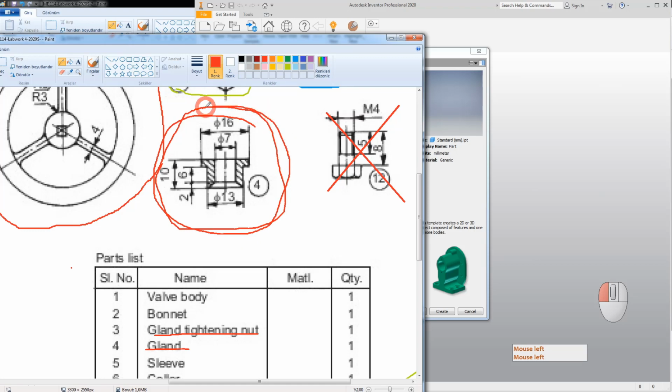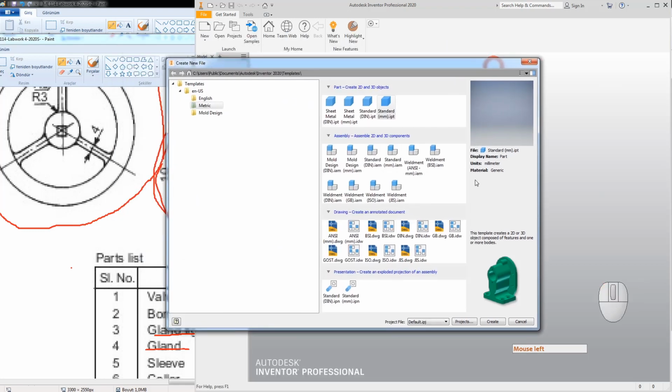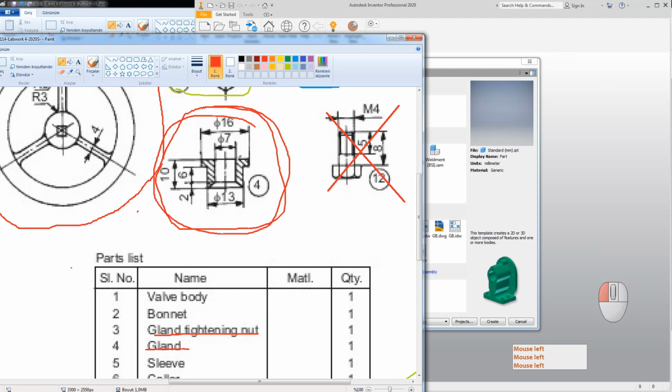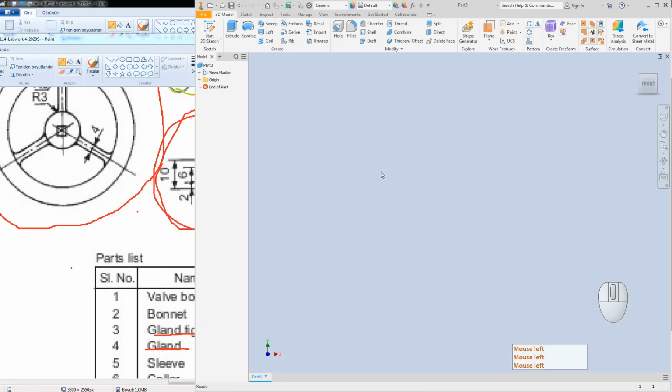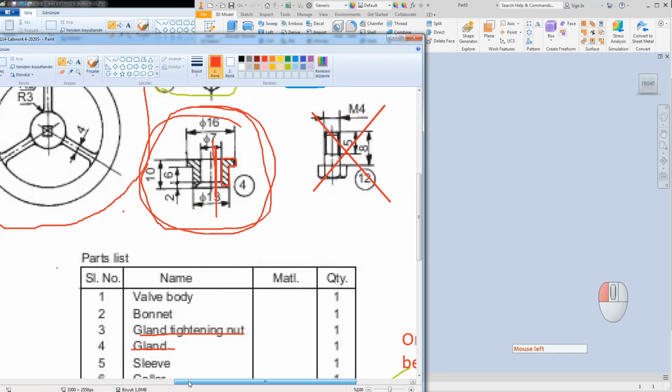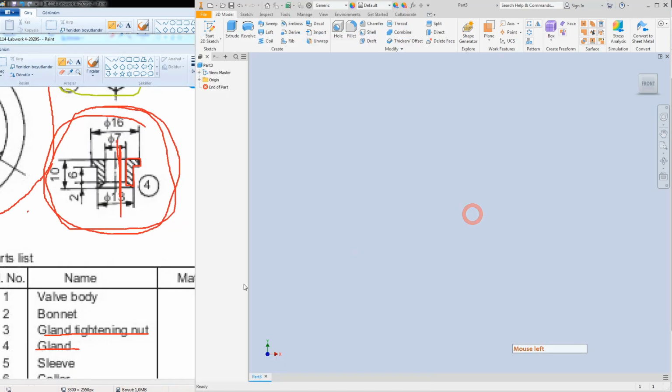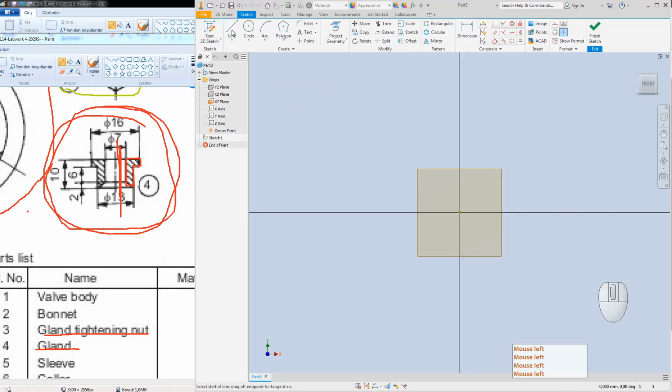This is also another cylindrical part. It's very easy to model it. I will just follow one side here, this outline, and we have only one center axis. Start a new sketch. I'll make to see a little bit. Have the center point visible, XY plane visible. Start a new sketch on XY plane.